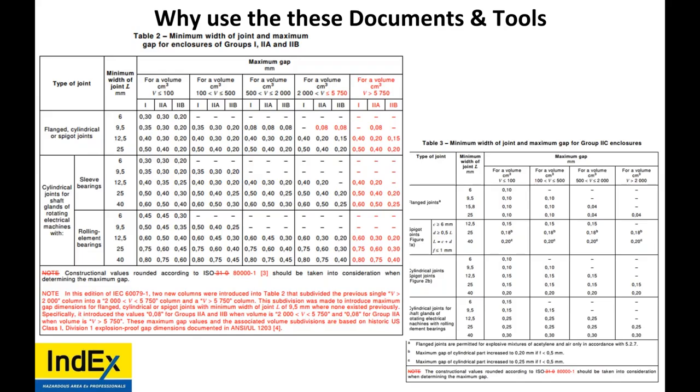Is it allowed to have more minor components inside it? So minor components, I'm not sure what you mean. If it doesn't come as part of it from the manufacturer, tested and certified with what's in it, you cannot change anything. For explosion proof, who can fix the final certification of the enclosure?